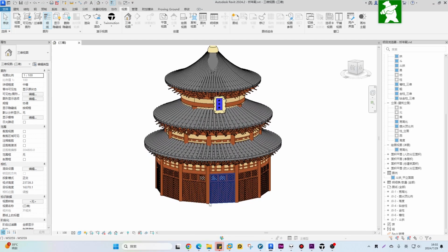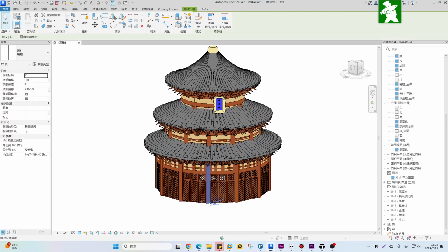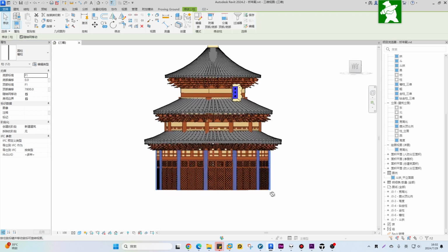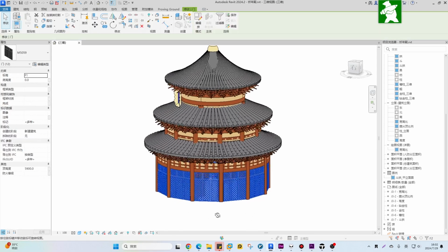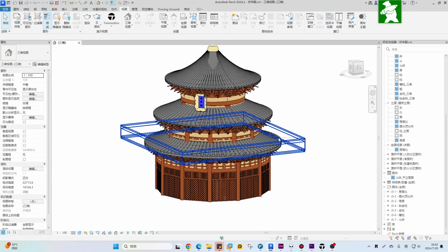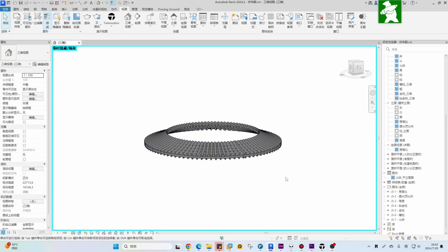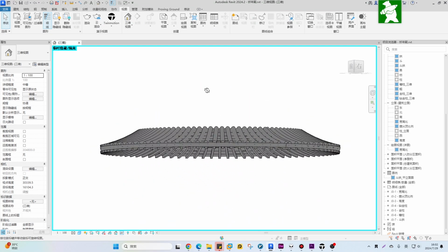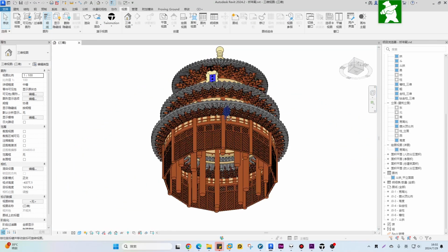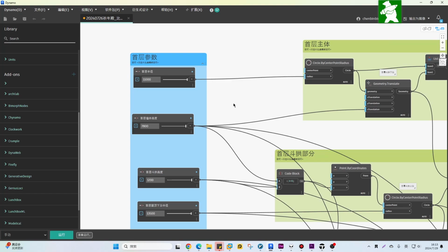two ways to transform the geometry created by Dynamo into Revit. One is to control the position of columns, doors, and windows through the positioning points in Dynamo, and the other is to import directly. In this case, there is no information and material, only an import symbol. This behavior is different from Rhinoceros 3D.